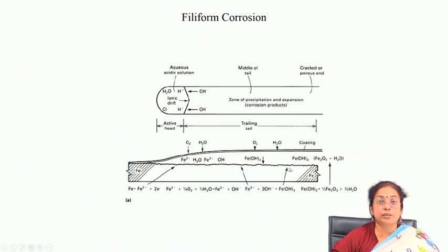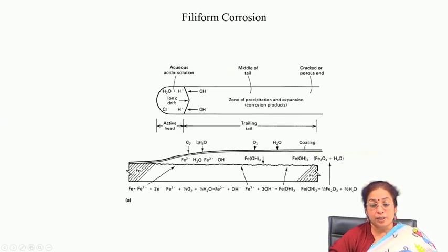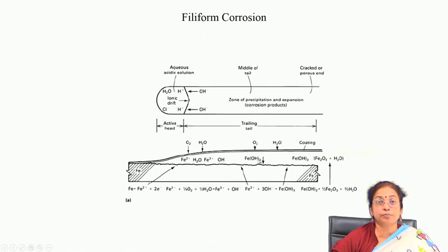surface, there is iron oxide formation, ferric oxide and also ferric hydroxide formation. If you look at the formation rate in different regions, you will find that it is higher in some regions; it is not uniform, because wherever there is a perforation or very small porosity, it is through that porous region only that there is migration of the water molecule, and then there is formation of iron hydroxide.